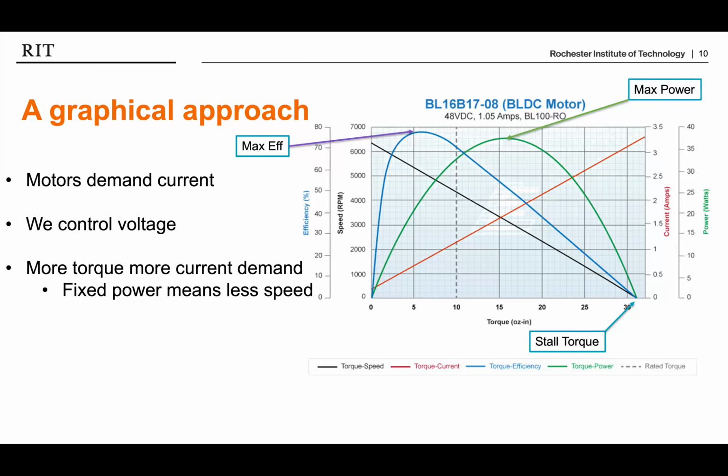Okay, so hopefully you've had a minute to think, and there's probably two realizations that you've had. You could design a system so that normally, on average, my torque is going to be somewhere really close to the peak efficiency for my motor. Because remember, I know what my torques are. I know what these are going to be from the mechanical design part. I need to pick the motor. So I might want to pick a motor that gives me the most efficiency. And if what you're doing is designing an electric vehicle or a drone or something battery powered, this is a really good tactic.